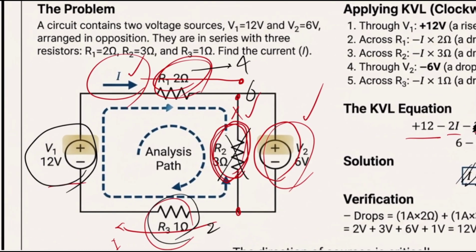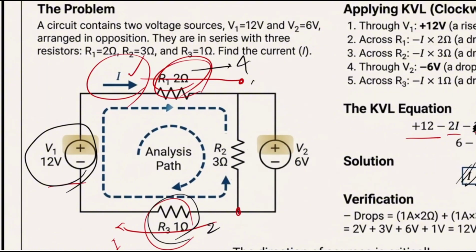When we were talking about the whole circuit over here, let me just get rid of that. When we were talking about the whole circuit, I told you that this R2 is going to make me some problem. Instead of getting rid of that and instead of just working with the current that goes this way, for example I1, because obviously I is going to be divided at this point, I somehow suggested that I can say I do have all of the voltage that I have over here. I know for a fact that R2 is going to have a voltage drop, right? The voltage drop over R2 is the same as the voltage rise in V2 but with flipped sign.